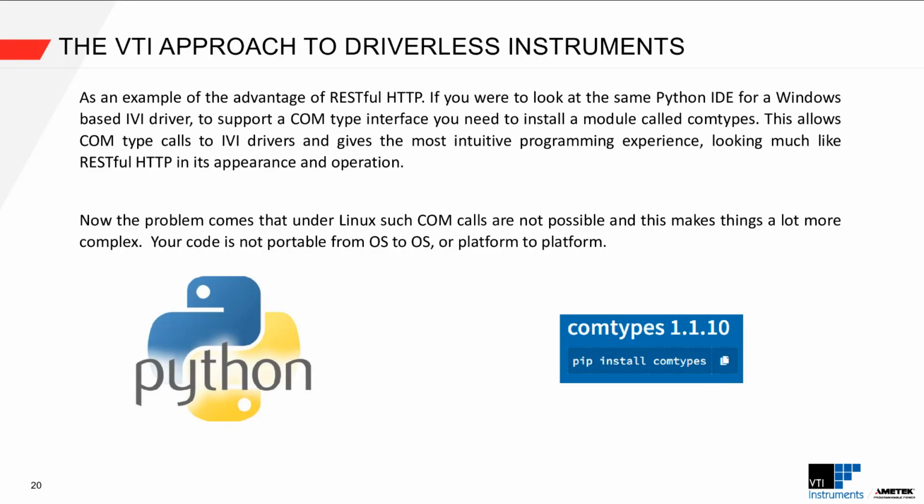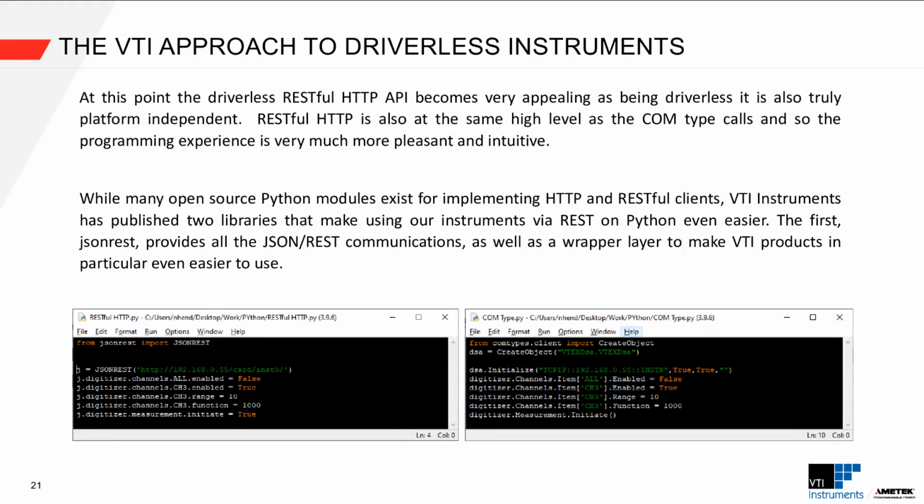Therefore your code is not portable from operating system to operating system or platform to platform. And that is where driverless really comes into its own. You can write your application under any operating system and use it in any other operating system. So you can start to see how important controlling your instrument with a driverless approach, and RESTful HTTP is a great one over Ethernet, becomes very appealing.